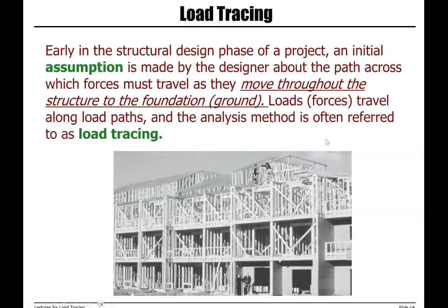Load tracing. Early in the structural design phase of a project, an initial assumption is made by the designer about the path across which forces travel in a structure, usually from top of this structure to the ground or foundation. Loads or forces that we have in a structure travel along what we call load paths, and the analysis method is referred to as load tracing.